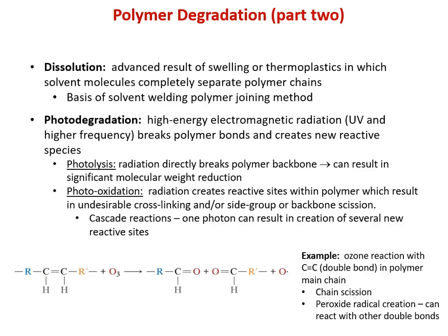And so this creates a rather bad situation where the very materials that we were using outdoors to be protective, because maybe we didn't want to have to deal with electrochemical corrosion of metals, are now being degraded by exposure to light. And again, there's always ways to engineer around this. We can put in absorptive pigments that basically absorb the light and prevent it from reaching polymer further down.